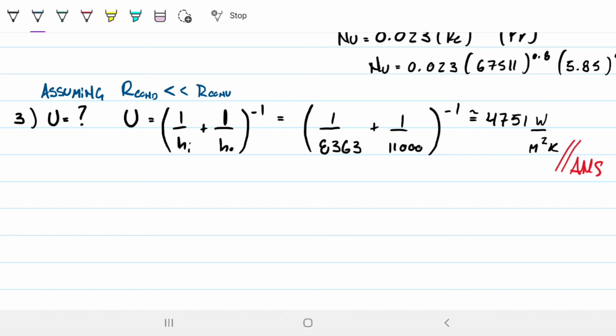And this comes from the thin-walled statement that we read in our problem statement, right? So going from the steam water pipe into the liquid water pipe into the steam, we would have the resistance of the water in the tube, then the tube, and then the steam. This one here is a conductive one. This one's way smaller than the other ones. So we need to add these two up to figure out what our convective heat transfer coefficient is.